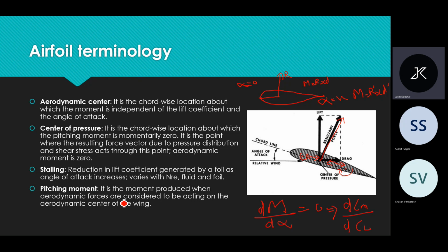And pitching moment. Pitching moment is nothing but just the aerodynamic moment. It is the moment produced when aerodynamic forces are considered to be acting on the aerodynamic center of the wing. It is given by the product of the resultant force and distance.